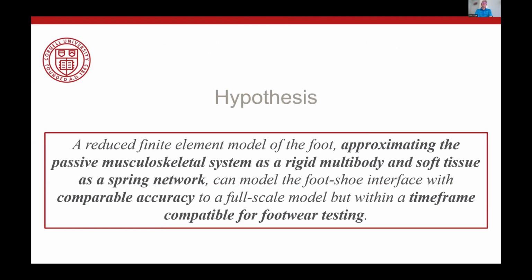I hypothesized throughout my work that a reduced finite element model of the foot approximating the passive musculoskeletal system, so bones and ligaments, as a rigid multibody, and soft tissue, which I'll approximate as everything else within the foot, as a spring network, can model the foot-shoe interface with comparable accuracy to these highly detailed finite element models, but within a time frame compatible for the footwear testing frame.